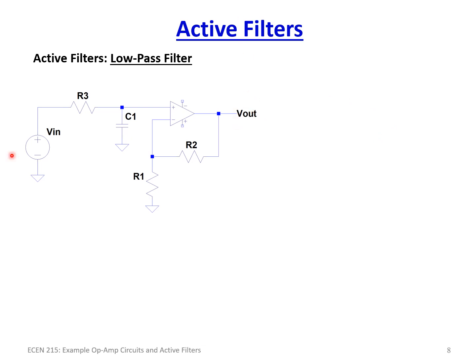So looking at this, the output is simply AV, the DC gain of the amplifier. In the frequency response lecture, normally this was 1, but now it is 1 plus R2 over R1, just simply the DC gain of this amplifier. And it's over the low pass filter term, the square root of 1 plus F over FC squared.